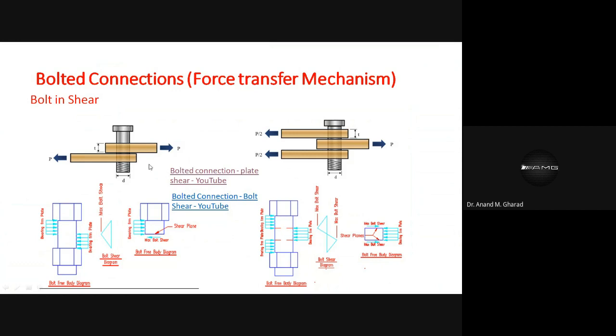Now, if I consider the bearing stresses, those may come into the picture for this kind of lap joint. Here, what do you observe? There are two plates, isn't it? There are two plates which are getting connected with the help of this bolt, right? And now, if I apply force in this manner, this portion of the bolt will get in contact with the plate surface.